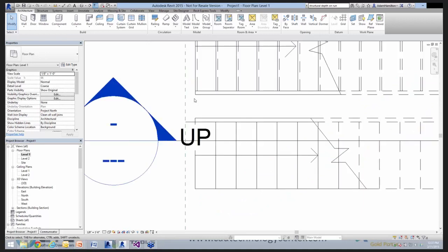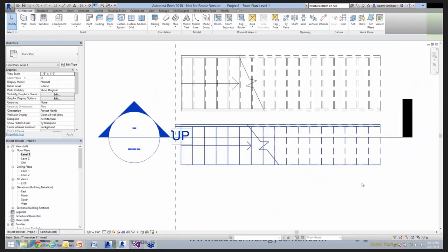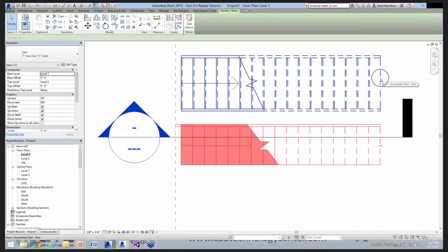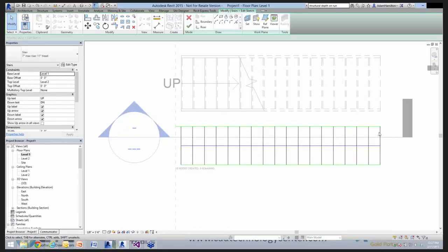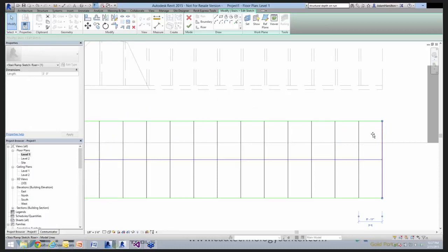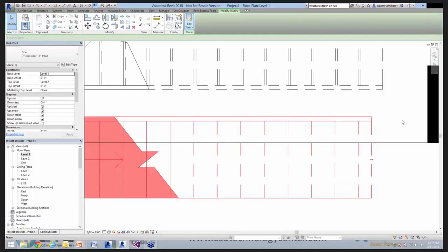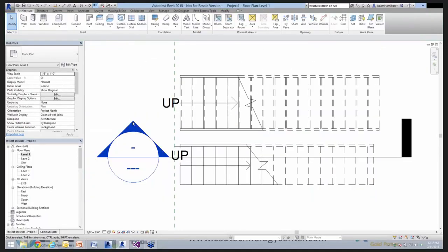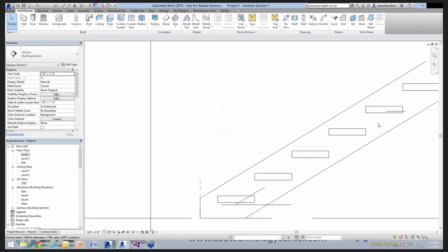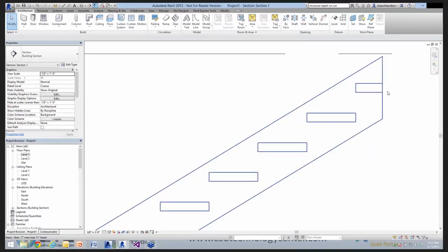Also, it's important to know that whether stair by sketch or even if you convert, if you wanted to do, say, a half-size tread or an extension like that, you can. You just have to modify this tread, and now you can create a partial depth tread. Again, that's always good if you're lining up with a slab up top or something like that and need at least a partial tread.